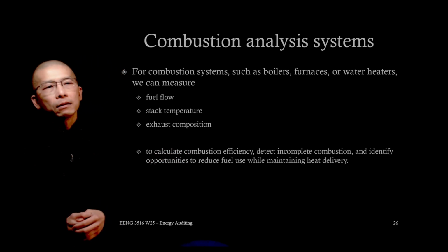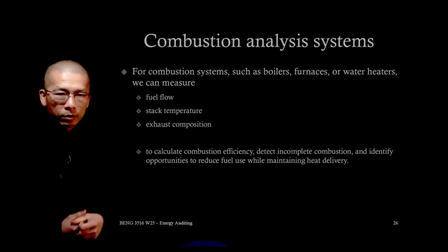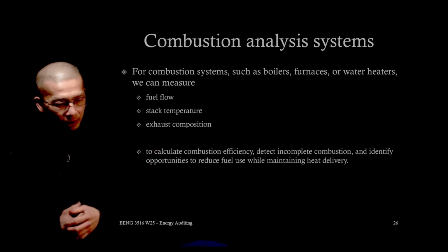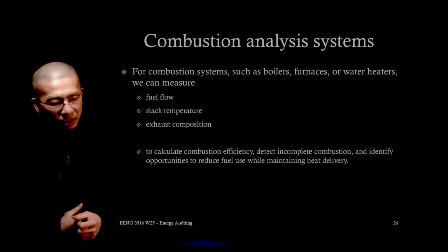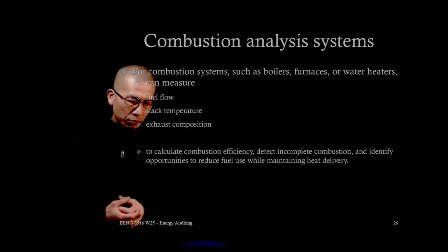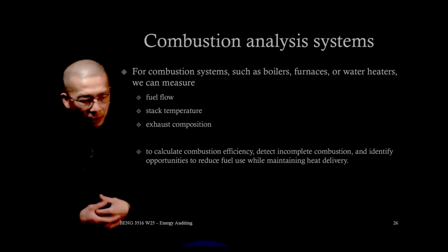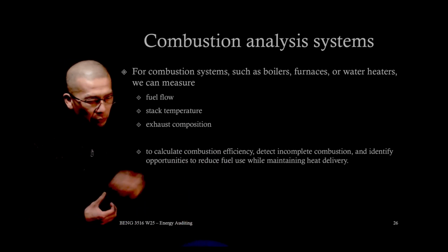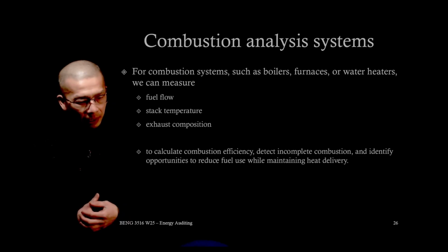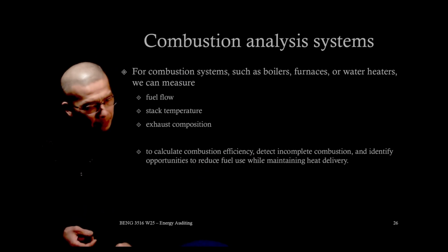Combustion system analysis. We already mentioned all these points: fuel flow, stack temperature, and exhaust composition, to calculate combustion efficiency and detect incomplete combustion. Those are the reasons why we want to do these measurements. We want to find these opportunities to reduce fuel use and maintain the heat delivery.